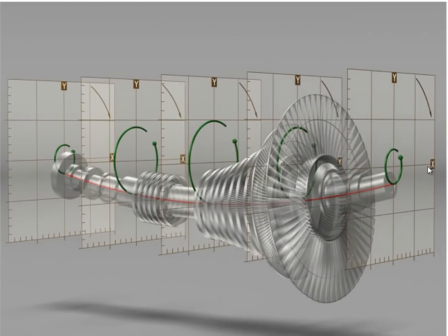There are so many details I'm leaving out, but just to give you a general idea, the orbit tells us what the center of the shaft is doing. So here we see this nice little orbit because it's moving in this small circular motion. More here, much more there, less and less, sort of similar, because that's what the shaft is doing, that's what the rotor is doing.